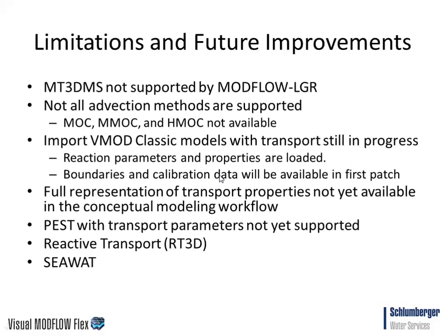So some of the things that we're working on improving for future releases and the limitations to be aware of. If you're working with MODFLOW LGR, transport is something that is not supported. So MODFLOW LGR does not support MT3DMS. It's a limitation of the USGS version, not something that we've added in VMOD Flex. We haven't implemented all the advection methods quite yet, so we've focused on the key ones. So the upstream finite difference, TVD, and central finite difference are in there. We don't have support for the particle-based methods, so MOC, HMOC, etc. If these are something that are of interest to you, then please let me know, and I'll do our best to get those out in a future release.